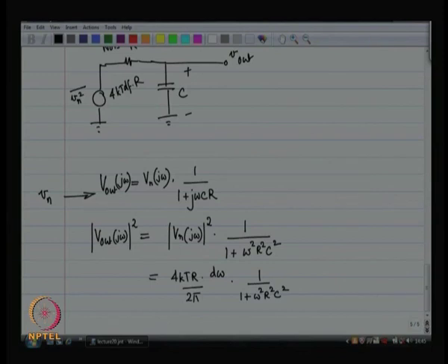If I look, I am going to get so much noise. Now, the noise at one frequency is not related to the noise at any other frequency, these are independent of each other. As a result, if I want to find out the total noise, you really have to take the noise voltage squared at each of these individual frequencies and add the total. That is how we are going to do it, right.